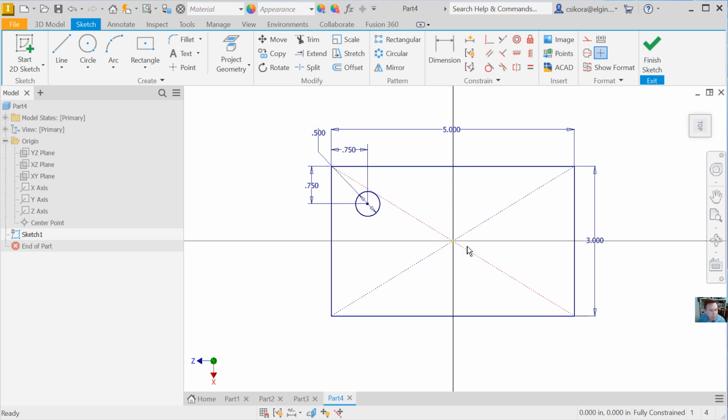Okay, all right. Now, rather than draw all those, which you can, and add dimensions, I'm going to show you a quicker way. So go to the line tool, and exercise 2 really deals with this, so I'm giving you a preview. With what you know, you could do this without what I'm about to show you, but I'm going to show you the cheat on how to mirror. So first, go to the line tool and draw a vertical line to the origin and a horizontal line off of it. Notice I didn't draw them all the way out. Oops, I only got one done. I hit escape before I finished the other line. So right about there. There we go.